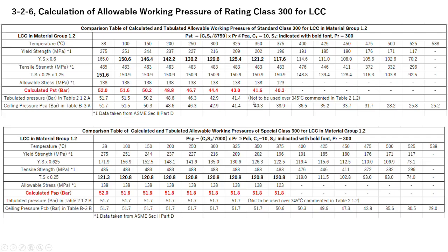So how about the valve body material? So ASME B16.34 also has a temperature limitation. So ASME B16.34 indicated temperature limitation for 345 degrees Celsius commented in table 2, 1.2.